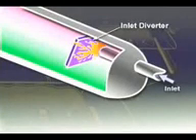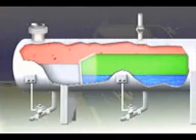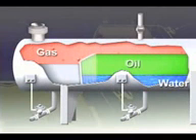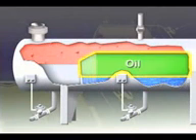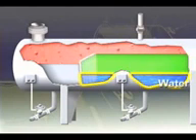Three-phase separators may be designed in either horizontal or vertical configurations. In a horizontal separator, fluid enters the vessel and hits an inlet diverter. The resulting sudden change in momentum provides the initial gross separation of liquid and vapor. The liquid collection section of the vessel must provide sufficient time for the oil and emulsion to form a layer or pad above the free water.